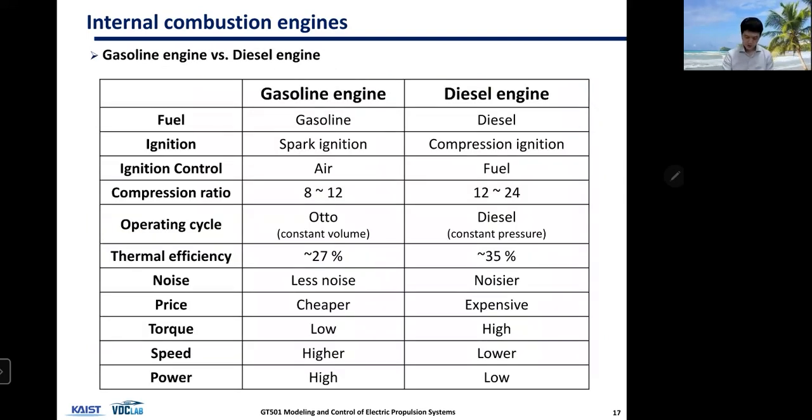And then there are two types of internal combustion engines. We mostly talked about gasoline engines so far, but there are also diesel engines. In fact, a diesel engine is much more efficient than a gasoline engine, and gives you better torque at low speed.